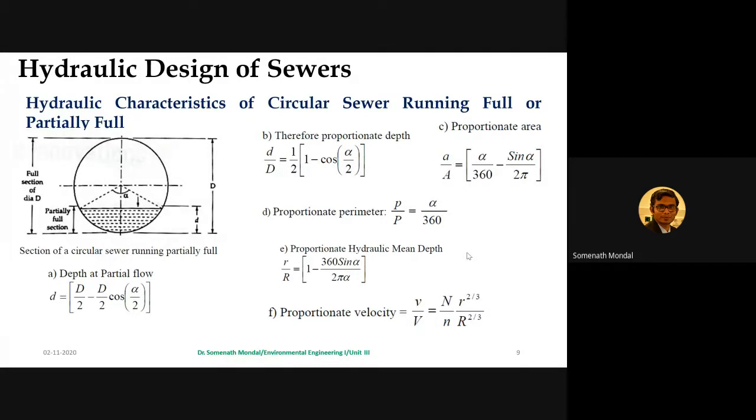and thus variation in hydraulic mean depth, and this is very true. Now if there is a difference in the discharge, that will directly create an alteration in the value of hydraulic mean depth, and due to the change in the hydraulic mean depth, there occur changes in the flow velocity, because it is proportional to the hydraulic mean depth to the power two-third.